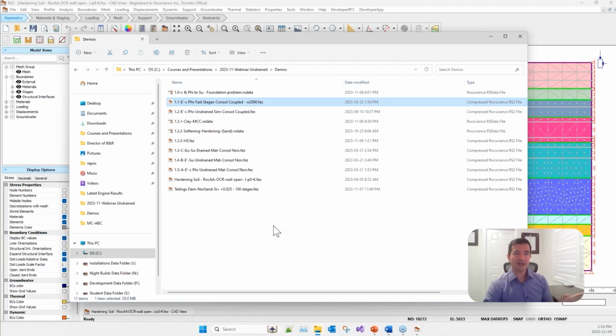I don't have the calculation in the presentation, but I can send the calculation to whoever asked this question. If W, which I was calculating, was more than 50, if I recall correctly, it would mimic the undrained condition. So for this one, I used 2000. You can have some calculation for the rate so that you can mimic the undrained behavior. That could be problem specific.